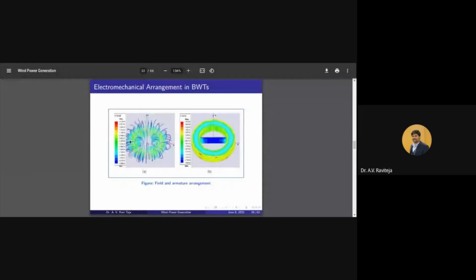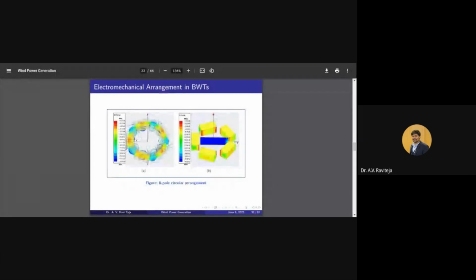Okay. So if I see the circular magnet, it is more flat, all blue, the same color. So I don't see much flux change. If I put the magnets in a circular fashion, bar magnets, then there is also only blue. So very little field is induced, and there is not much change. So if I place a coil in the middle, then it won't have any voltage induced at all.